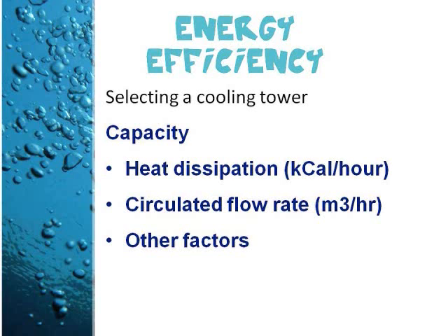Cooling towers are usually specified to cool a certain flow rate from one temperature to another temperature at a certain wet bulb temperature. When the size of the tower has to be chosen, then the approach is most important, closely followed by the flow rate, and the range and the wet bulb would be of lesser importance.